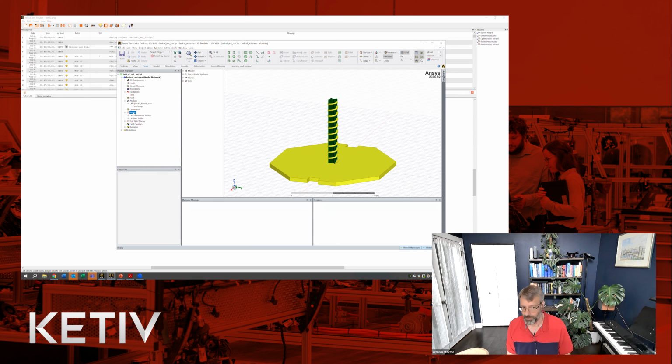And the other preparation item that you should do is for the results. Normally you would create a modal solution report and do a rectangular plot for your, say, S parameter. But in this case, I've eliminated all of those graphic reports and gone in favor of a data table here. And so I've set up a data table for my S parameter 1,1 and for my gain for this antenna. And then you also want to right click on each of those tables and export them.